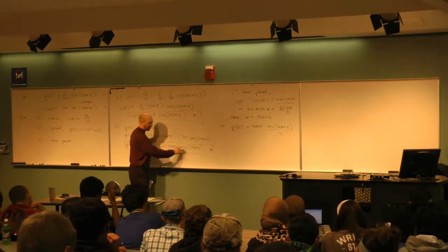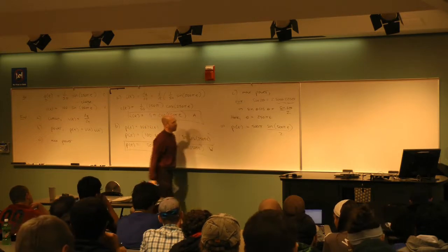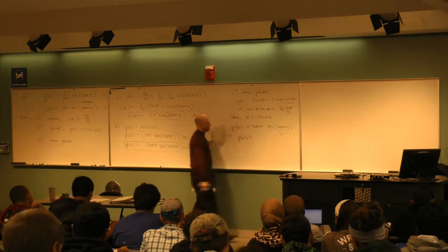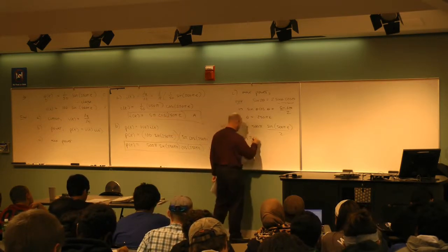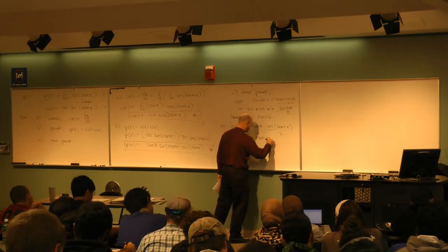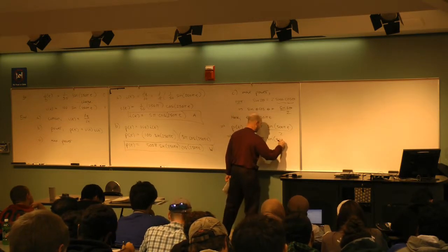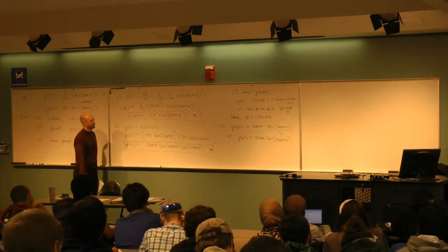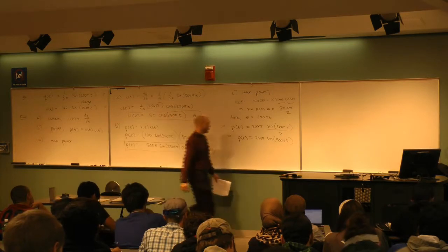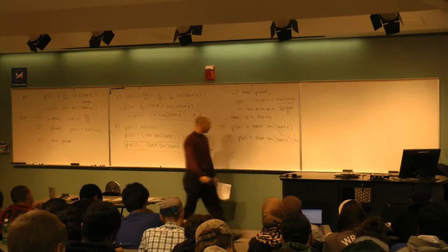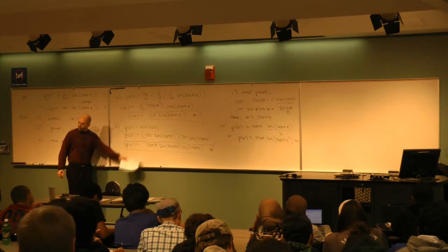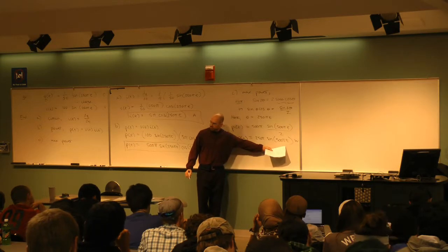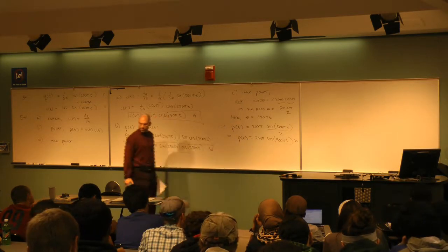So I recognize I have a sine times a cosine of the same angle, therefore I can apply this half angle formula. Okay, and so power, I can cancel out the 2. I'm going to get 250 pi times the sine 500 pi t. Interesting. Okay, that's also in watts. So now, this expression looks quite a bit simpler than this one. All right, this one's got a sine multiplied by a cosine. This one only has a sine with a different frequency.